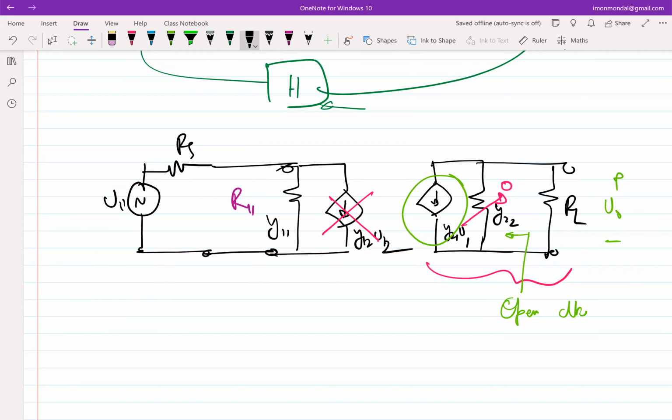Correct, exactly. There is a drop, right? So that's the issue. So this is your V1, and the current that you are taking at the output port is proportional to V1. So if V1 is lower than what it can be, then the current that you are driving at the output port is potentially lower. So ideally, you would want maximum signal transfer, or maximum current into the final load RL. Since the current is proportional to V1, you would want V1 to be as high as possible.